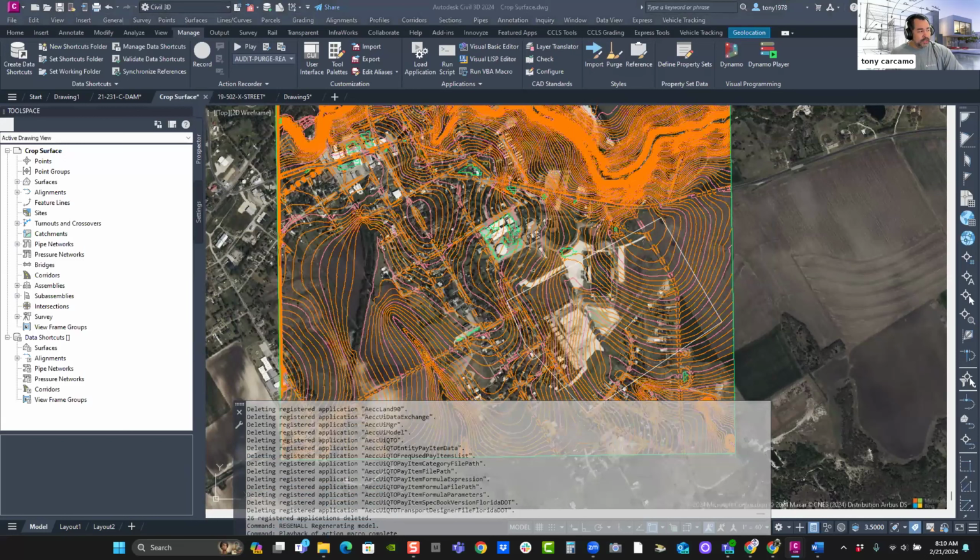Now, it's a little difficult when you start using something where you're selecting an object, then it gets really, really complicated. It works best for something you're not selecting. So let's say an audit, a regen all, a close. Maybe use that at the end of your design where you're about to close a drawing. So I might run an audit and then run a dash purge and then close, and you can just have it as a one-click option. So it's a nice little tool to have. How many people actually created one before and use it throughout their design, the actual recorder?